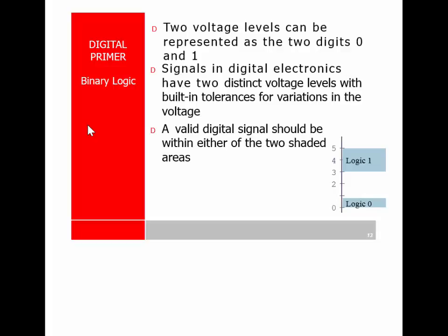Most digital electronics that we see today, including the microprocessor we're using in this lab, are 3.3 volts instead of 5 volts. Traditionally it has been 5 volts, and it's been 5 volts since 1975 or so, when the first digital transistor family came out. Texas Instruments was the first to put out a lot of them; the 7400 series started, like I said, in 75, 73, somewhere in that neighborhood. It's been 5 volts until about 4 or 5 years ago, and now I'm starting to see some 2.7 volt